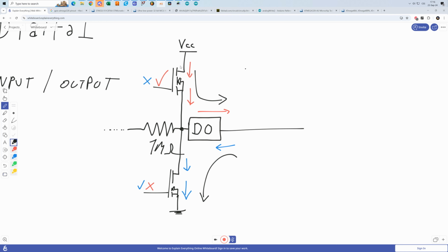A push-pull configuration is a high power drive, meaning it can deliver sufficient current for most applications. The current it can provide usually is in tens of milliamps, which should be more than enough for what a microprocessor should do. Actually, if you want to connect, for example, an LED to such a circuit, you will even need to add a resistor because the drive is that strong that it would destroy the LED if it was connected directly to ground or to the positive supply rail.